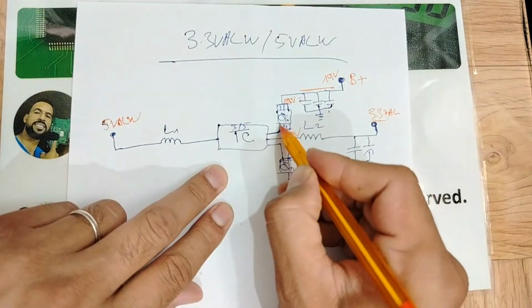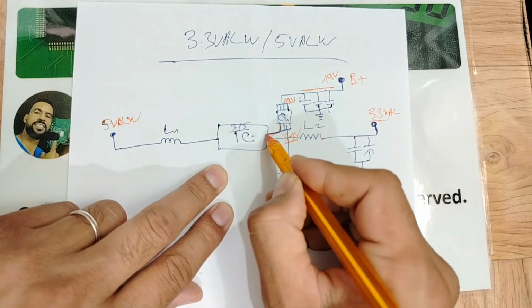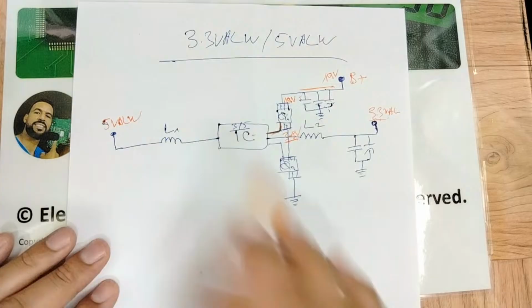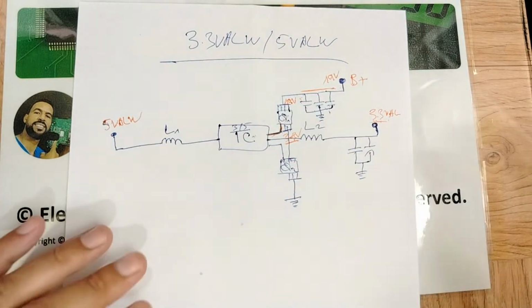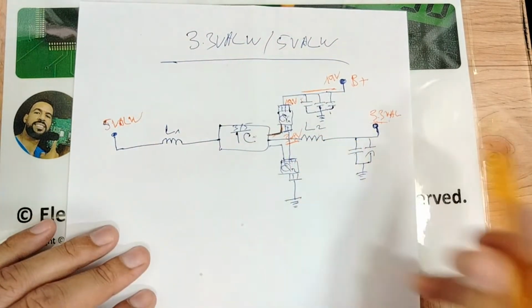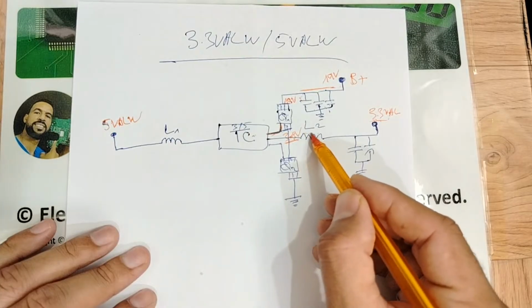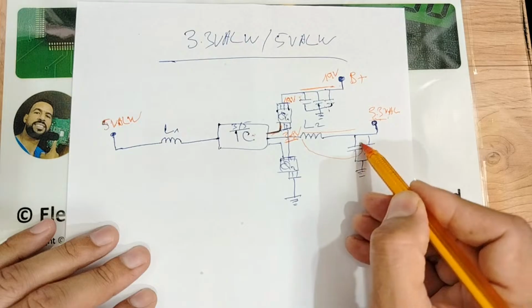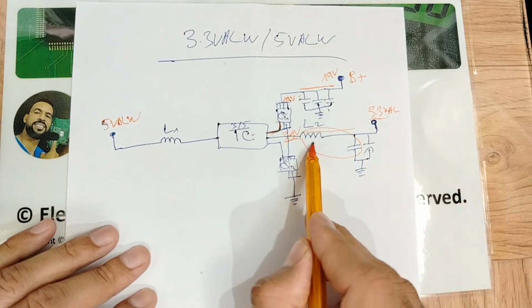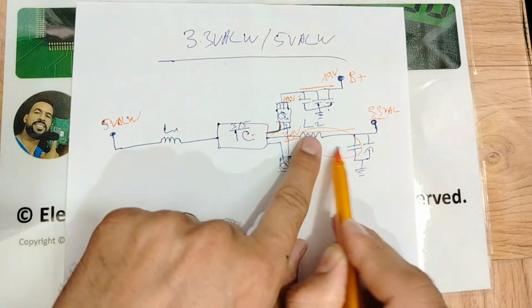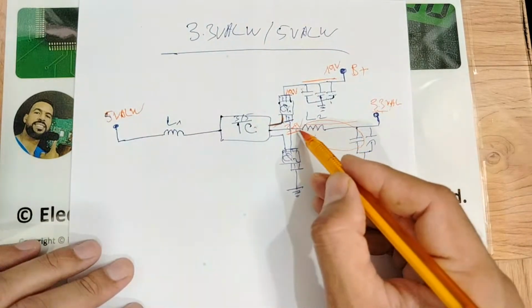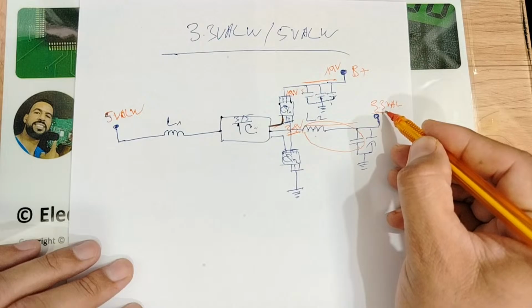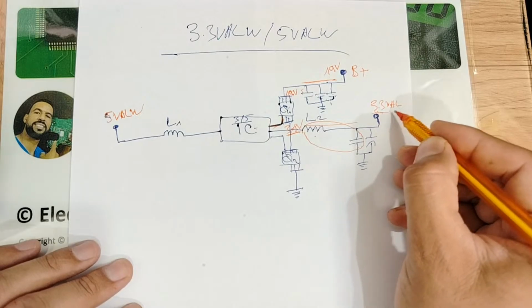Because of this control signal. This is the controller that controls the MOSFET. Okay, my friends? And of course after that the 3.3 volts will pass through this inductor here. Basically these 2 components, the coil and the capacitor, are here for filtering, to filter the 3.3 volts in order to get here a pure and exact 3.3 volts on this side.